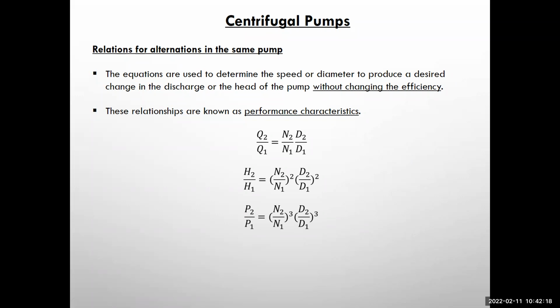Now tell me, for the specific speed, do we have only the dimensional specific speed expression, or do we have the dimensionless also? For specific speed, how many expressions we have? 2. In US, which one we use? But we act like we are using dimensionless numbers.